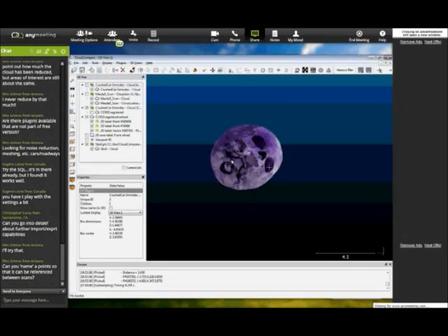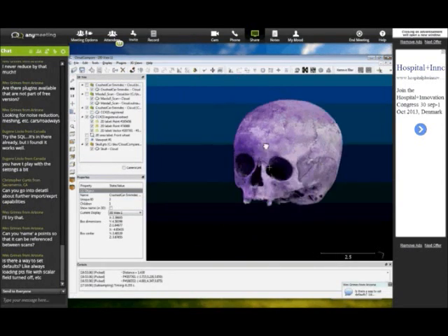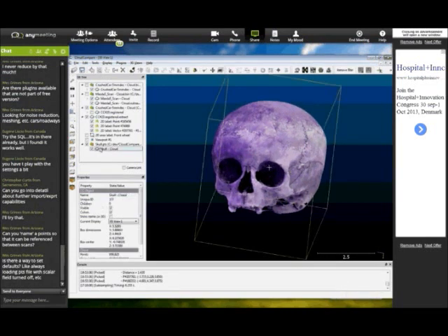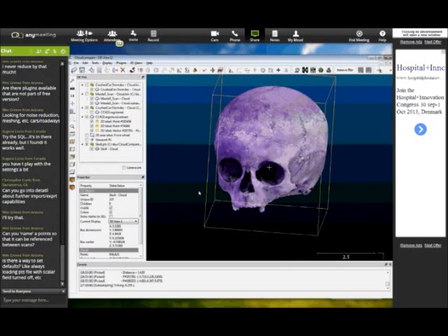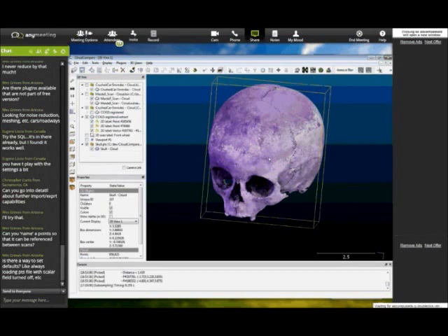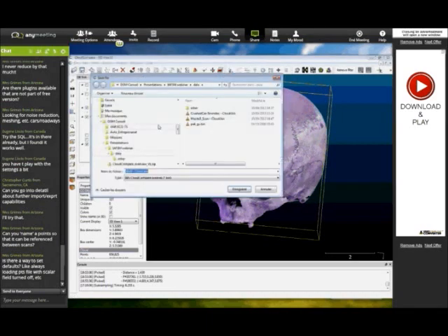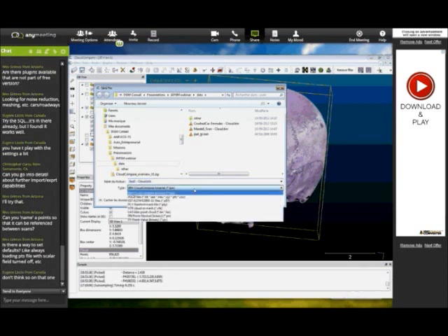And when you want to export entities, if it's a single entity, for instance, I simply selected this cloud. You can click on the floppy icon, which will display the save dialog, and you can choose between several formats. The formats displayed here depend on the entity you have selected, either a mesh or a cloud mainly.